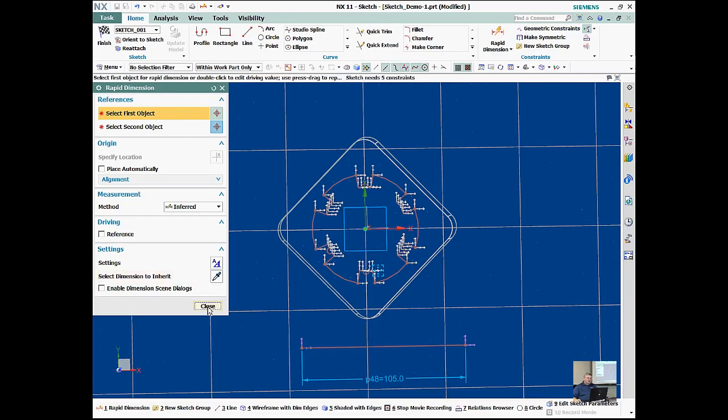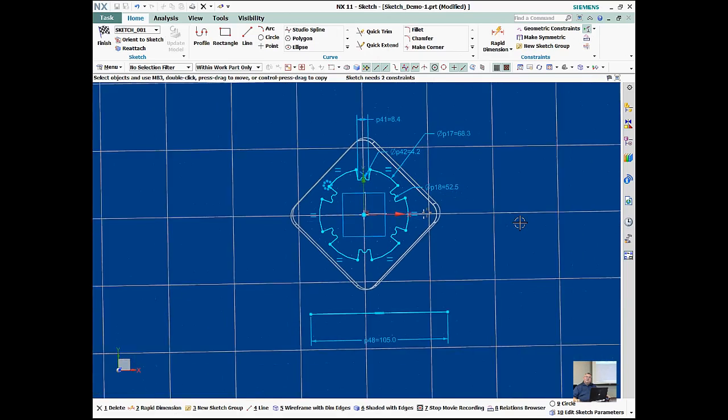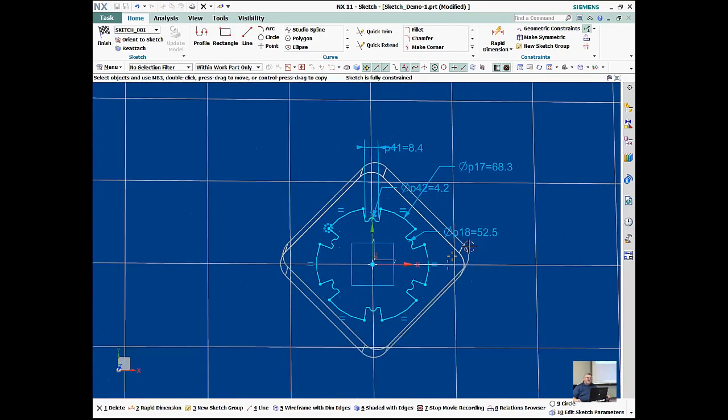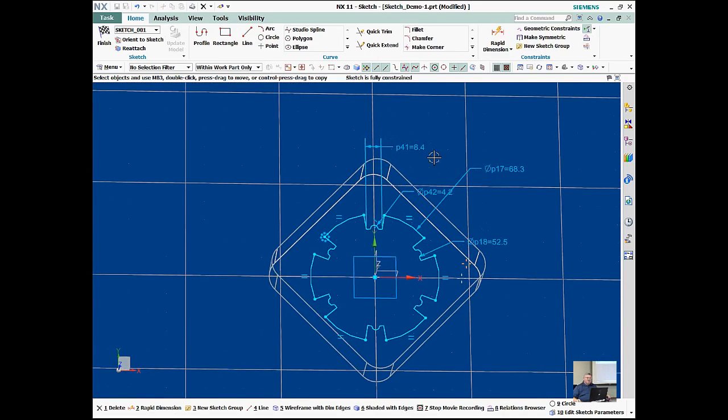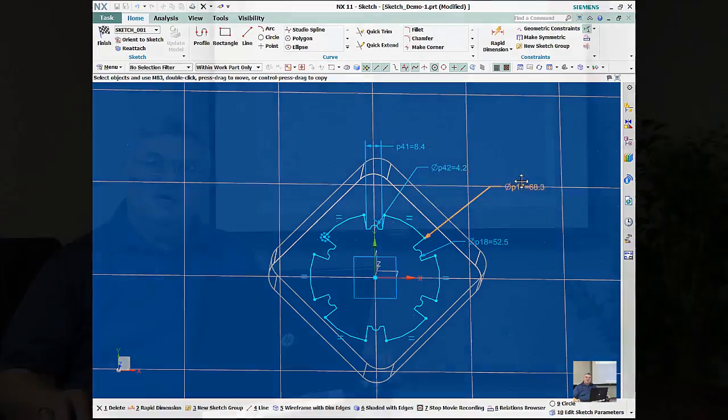Now, you say, well, fine, the line is 5% larger, but I've lost all the dimensions in my sketch. Well, that's not quite true, because I can now select the scalable group constraint and delete it. And when I do, all the dimensions that were used to create it come back. Now I'm going to delete this line because that's really not part of my sketch, but you now notice that each one of these parameters has been updated and is 5% larger than what it was before.